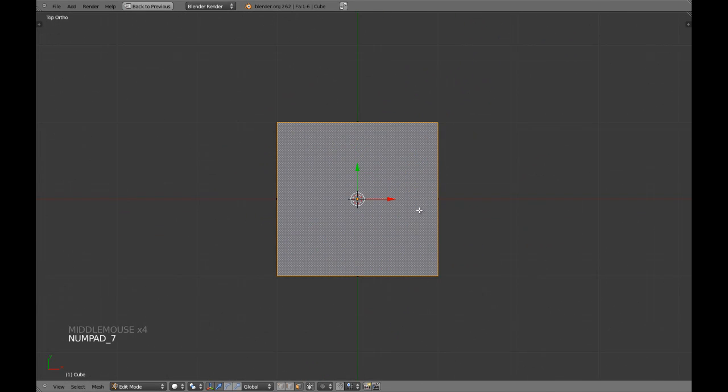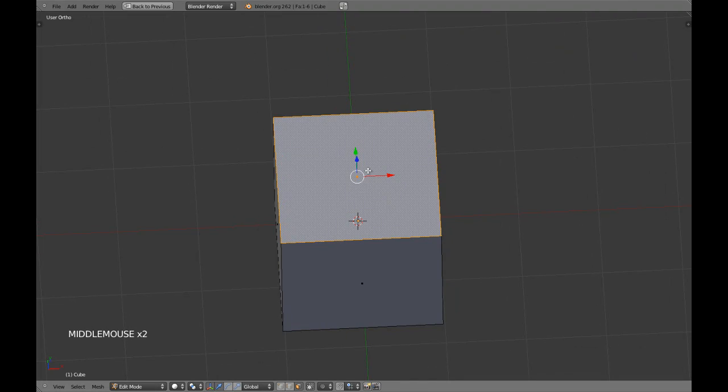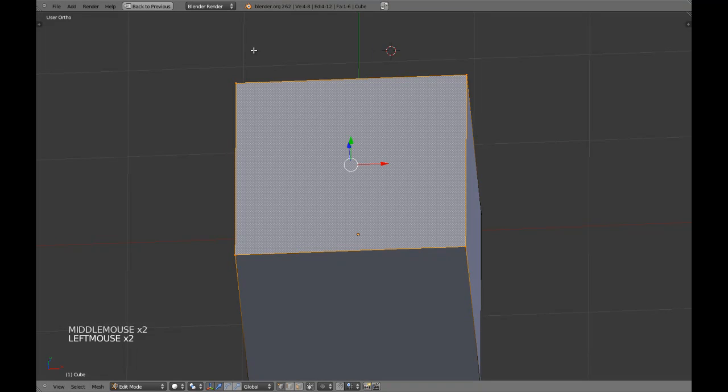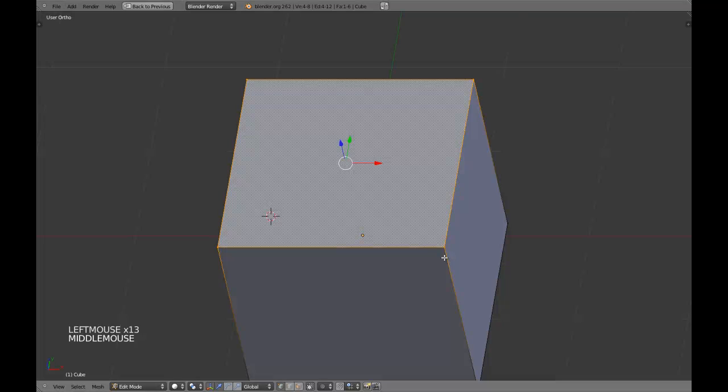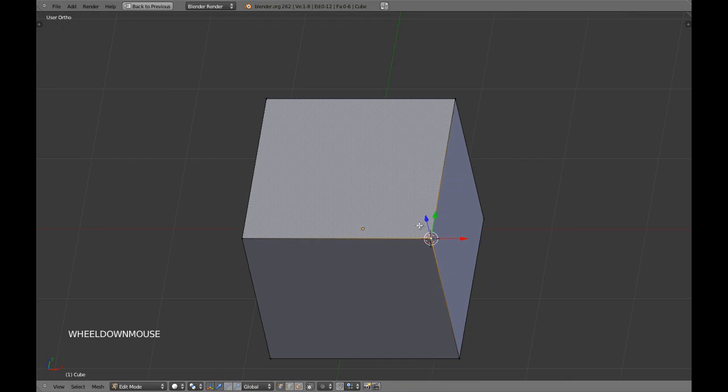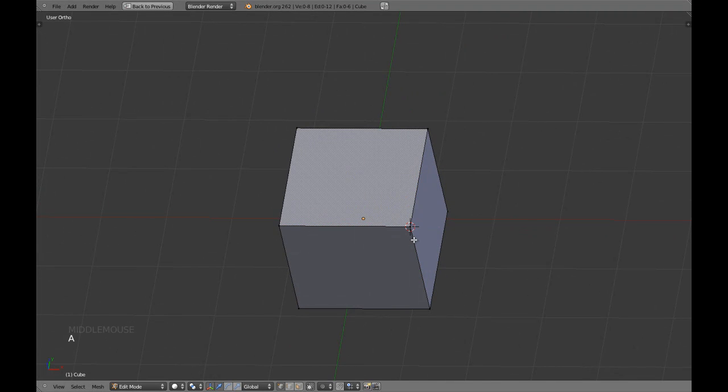But you can modify that, for example, with your 3D cursor, which is this, that each time you click it appears. For example, if you select this vertex and you activate the snaps, or you use the snap with Shift S, you can use Cursor to Selected. Okay, and then you have the cursor just over that vertex.